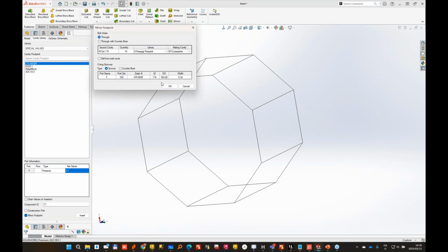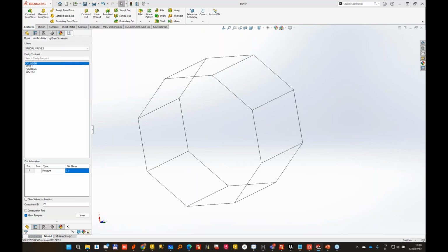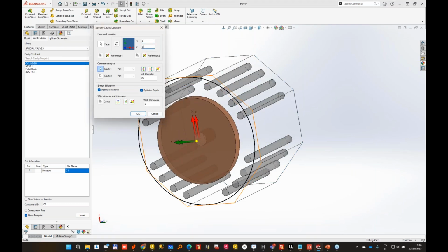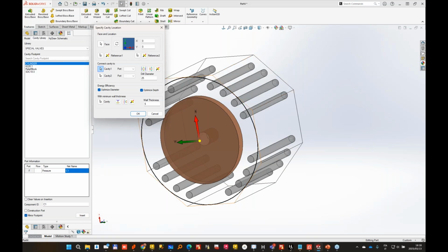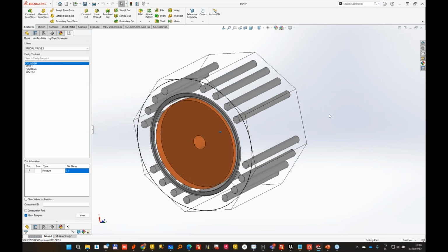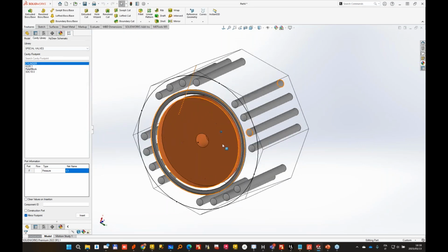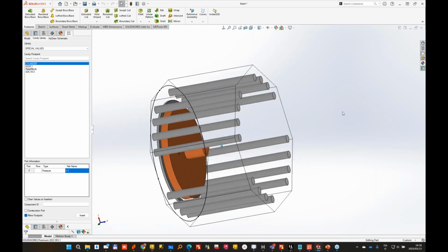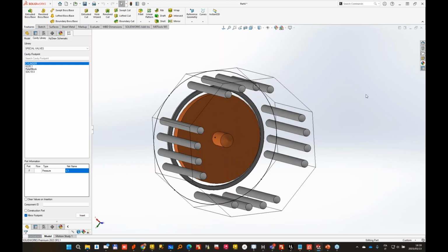It's possible to define standard O-ring grooves in the library. Okay, I want to place it here, and I put in the origin of the part 0, 0. When I do that, MDTools creates my through bolt holes, the O-ring groove, and everything. So I'm ready to start my design.